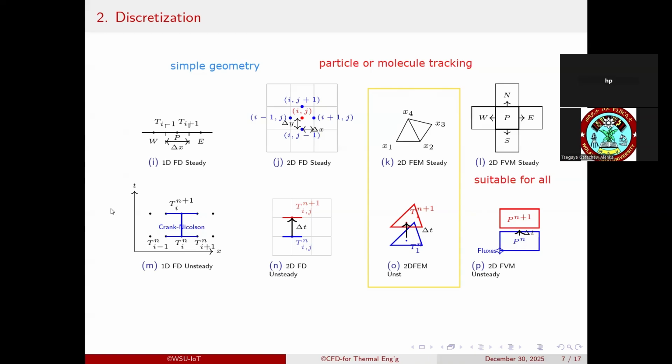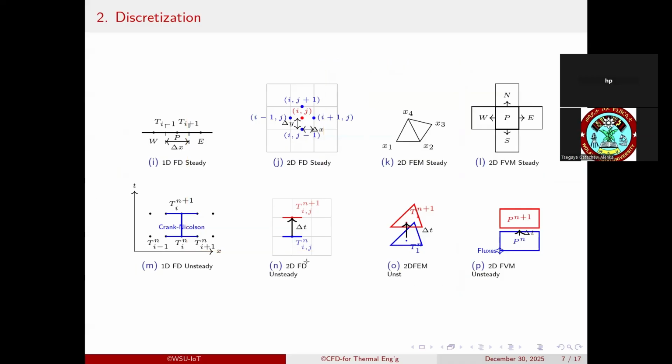The last category in the column of discretization illustration has the broadest applicability of all CFD methods for almost every kind of problem. In finite volume discretization, dependent variables exist or are analyzed at specified locations within or on the boundaries of discrete fixed regions called volumes.